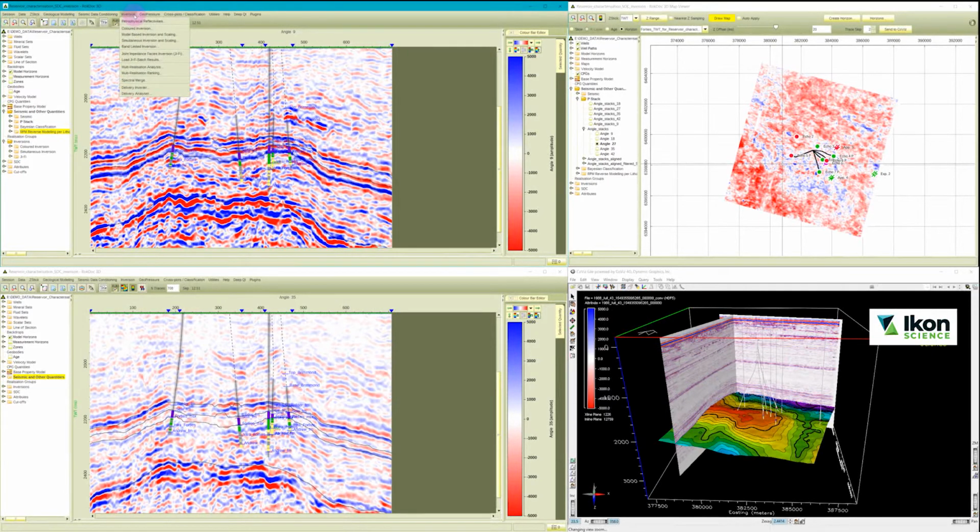The add-on provides access to multiple seismic inversion techniques. These are different methods of generating elastic properties from seismic amplitude data. We will review the colored inversion tool, a robust technique for generating relative and absolute attributes from single stack data, as well as a model-based approach. For this, we will focus on the Simultaneous method, where multiple angle stack seismic volumes are inverted for elastic impedances.